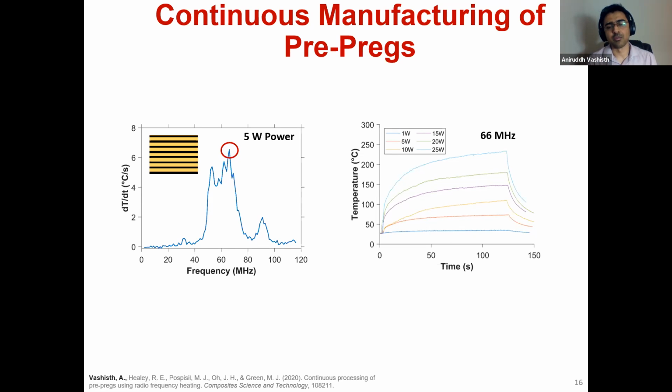I think the interesting thing would be what type of heating ramp rates you would want to achieve, or whether using RF energy changes the microstructure of the polymer, or might degrade the polymer you're trying to bond. But I'm fairly confident that if you use carbon nanotubes, carbon nanofibers, or even carbon black, you can achieve those temperatures, I would say, with less than 500 watts of input RF power.